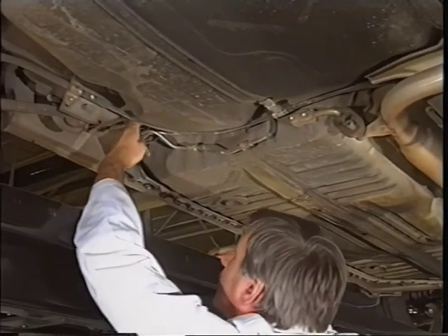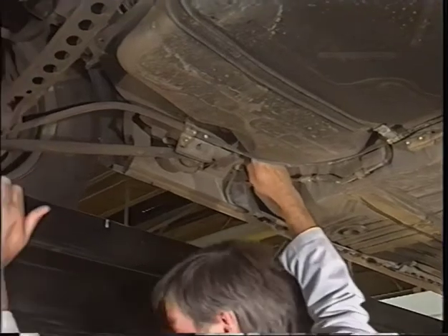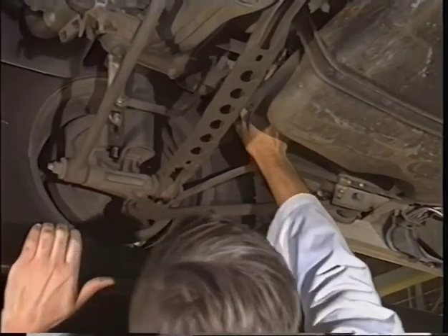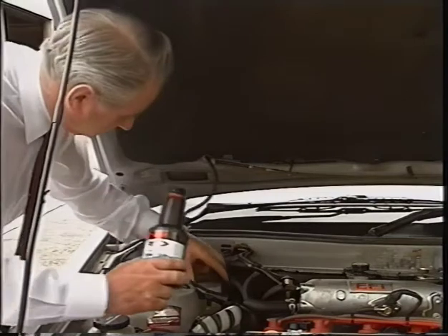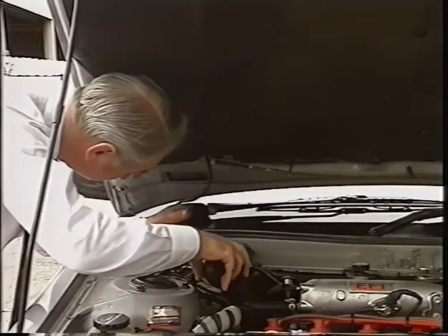It will, however, still be necessary to visually inspect the master cylinder, service brakes, brake pipes, valves and hoses for signs of fluid leakage. This will allow for the possibility of the master cylinder having been topped up just prior to the vehicle being brought into the workshop.